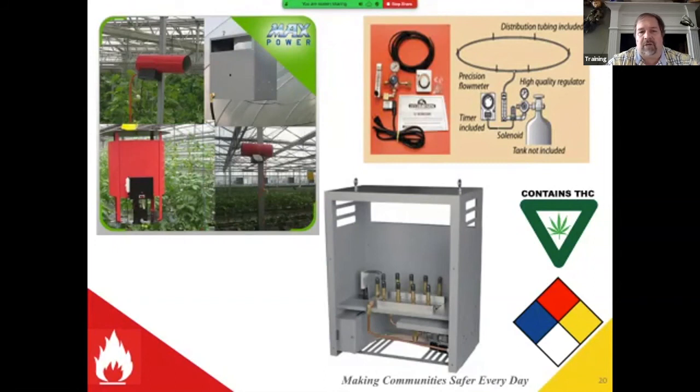we'll review this and we'll point this out and try to vet this out ahead of time. The majority of people want to install these so-called CO2 generators. They are unlisted equipment. And as soon as we start pointing out the fact that it's going to require you to provide an additional cooling capacity, an additional dehumidification capacity, so you're dumping heat into the space to go and remove heat from the space, it doesn't make a lot of sense. Mm-hmm. And once this is pointed out to them,